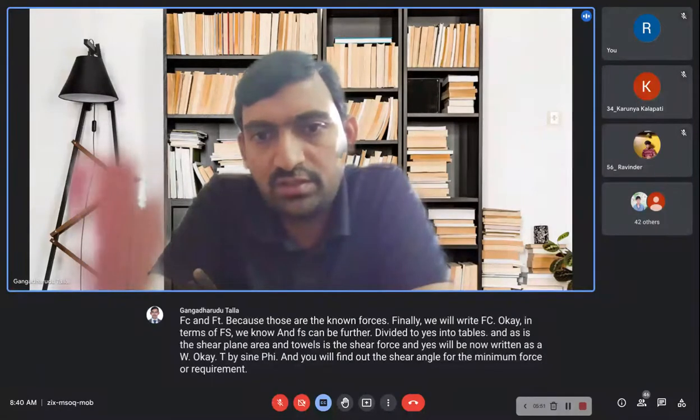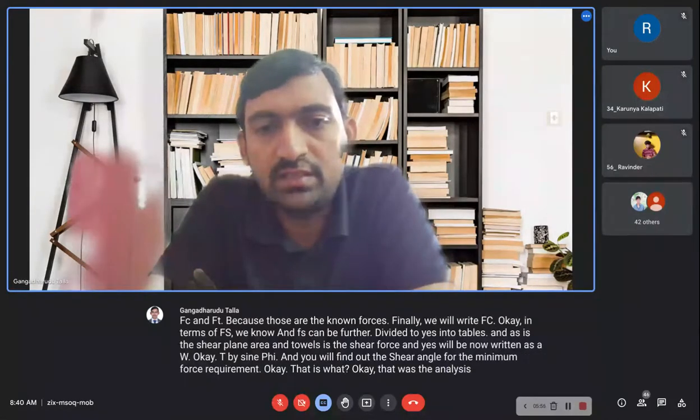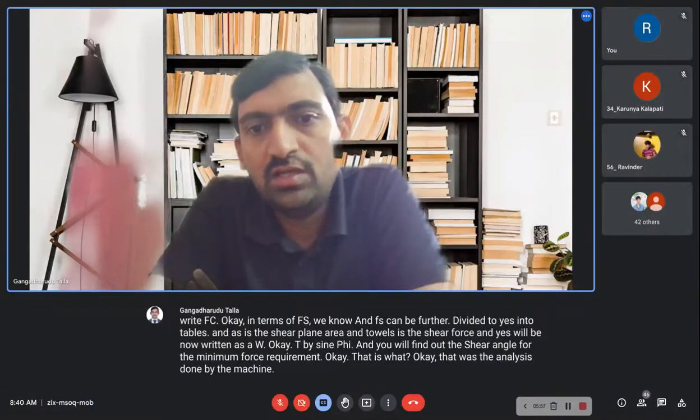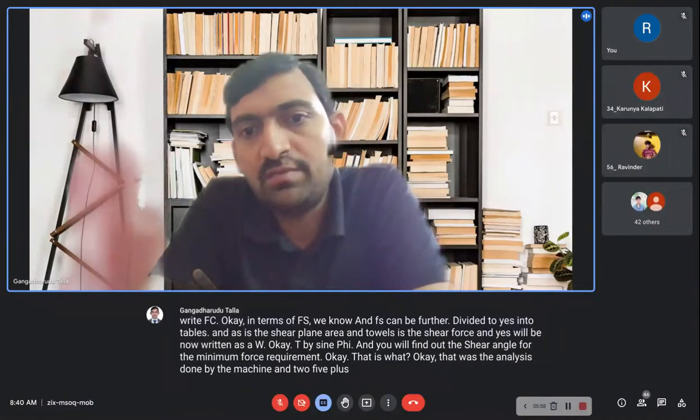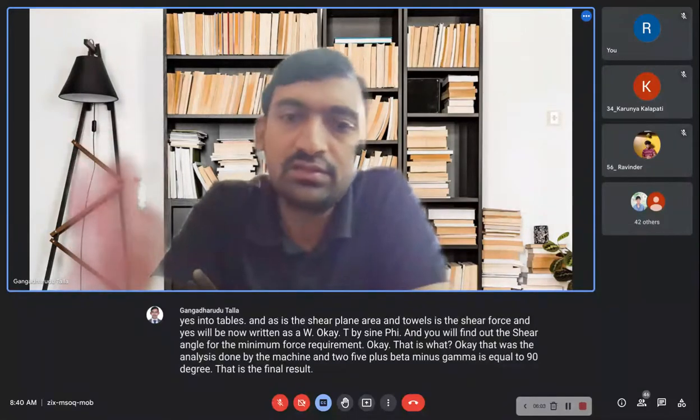Okay, that was the analysis done by Merchant, and 2 phi plus beta minus gamma is equal to 90 degrees. That is the final result.